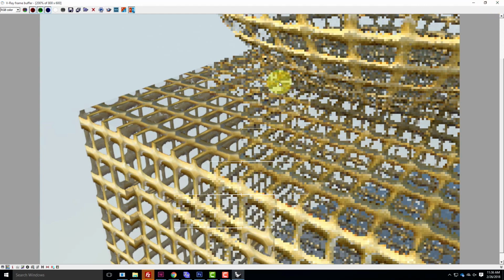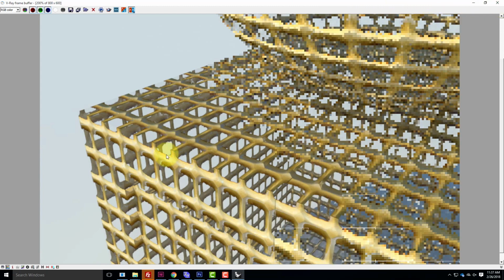I'm not going to let it finish. Notice, though, that the rendering times went way up, because now it's calculating the rendering of this surface, and then as we look through, we're doing the backside of this. The only issue with this strategy is that if you had some displacement to it, let's say you had the wire with a half circle on top, the underneath side is going to be the inverse of that. So when you're looking through it, it's not going to show the other half of the circle.